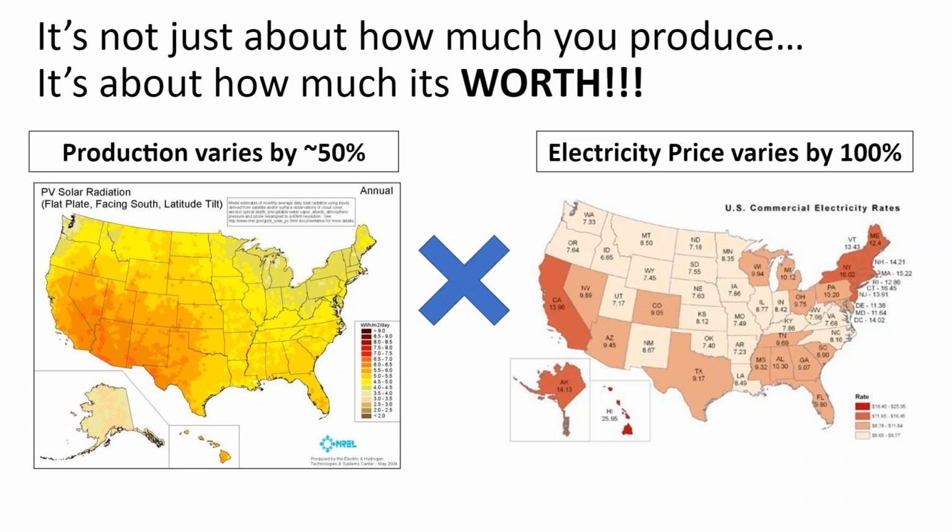But on top of the raw cost of electricity, it then becomes how you are billed for electricity. And there are flat rate structures. There's variable rate structures, which I love because with a variable rate structure, you can design the system to fit the rate structure and not the roof or the electric bill, but say, what's the most bang for my buck? And with variability, you can find optimization and have a more cost-effective project rather than a lot less cost-effective project.